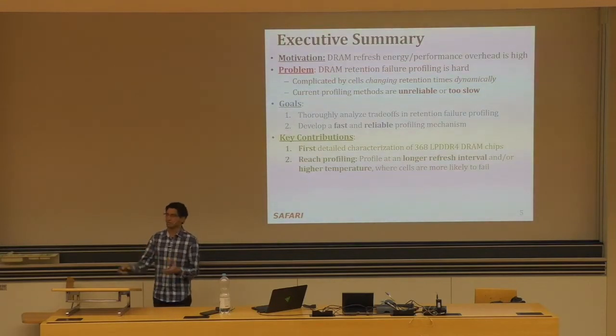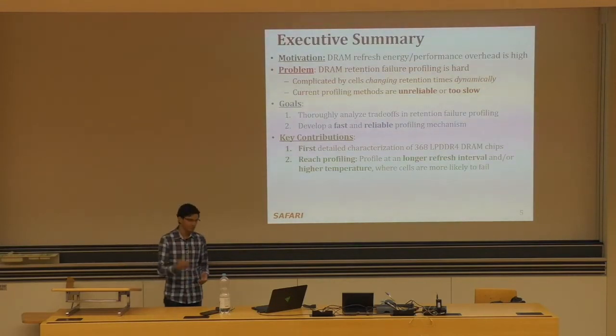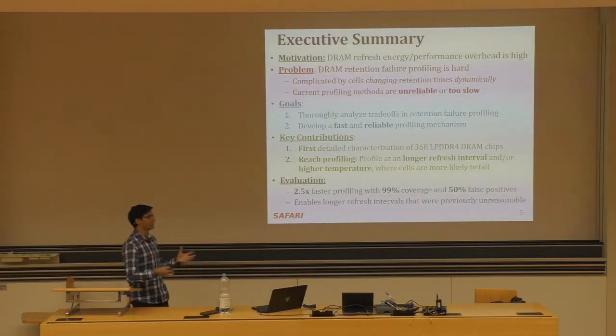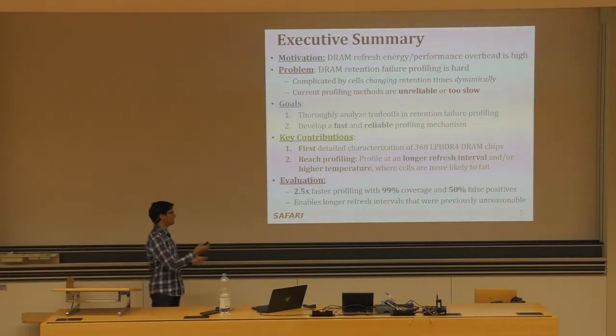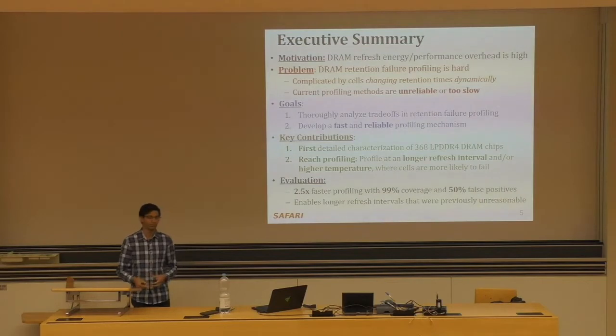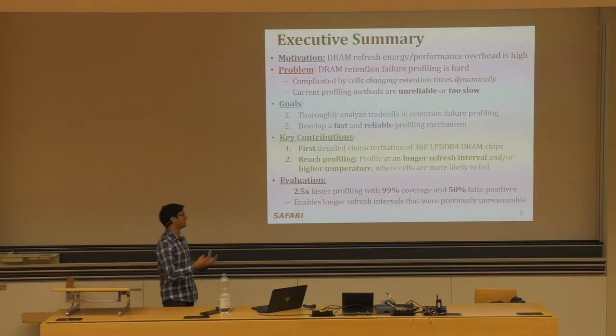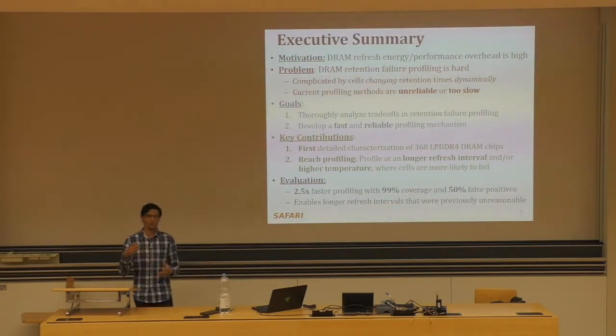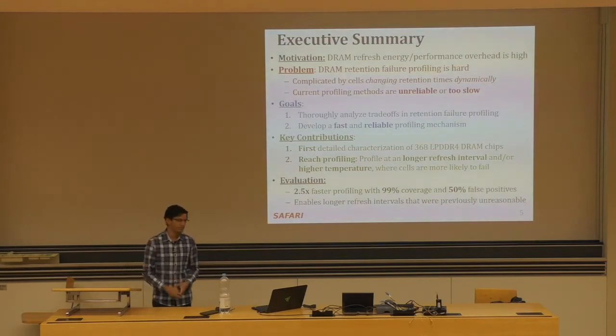And this is because that's where cells are more likely to fail. Through our evaluations, we find that reach profiling gives us a significant performance and reliability improvement over prior works, and it actually enables longer refresh intervals that were previously unreasonable due to profiling overhead.